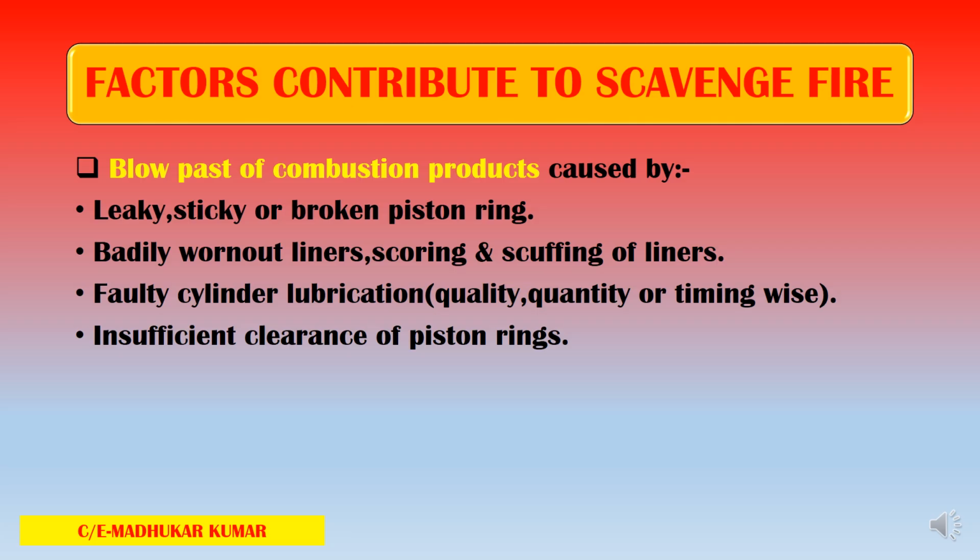Piston ring condition has to be up to date, and that's why the scavenge space cleaning and inspection is done and monitored. Badly worn liners, scoring and scuffing of liners are also one of the causes. Faulty cylinder lubrication, in quality, quantity, or timing, is also going to cause scavenge fire.